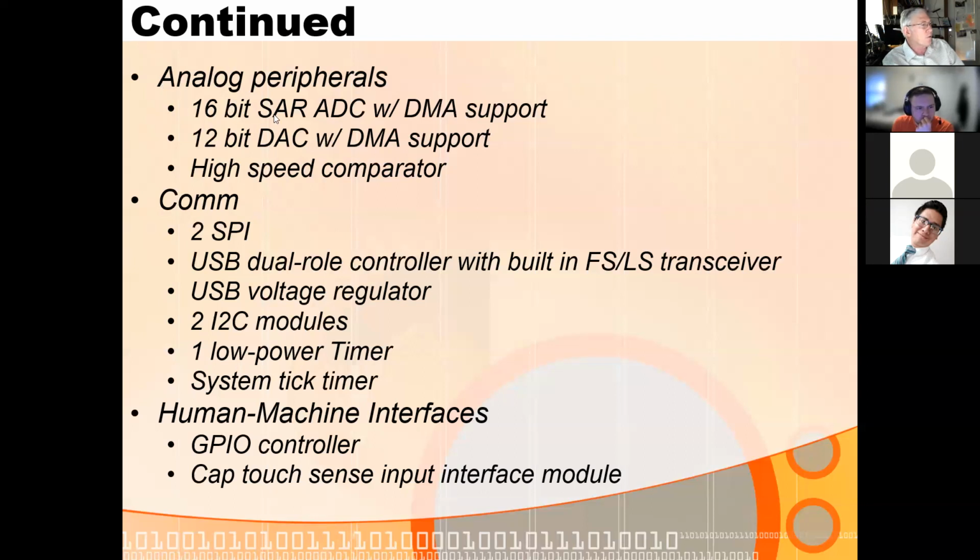This ADC is very, very advanced. It can take multiple readings, like 2, 4, 8, 16, 32 readings. It can average them together before it reports a value. So it can read your ADC input 16 or 32 times, do the conversions, average them together, and then give you that average signal, which is really nice.